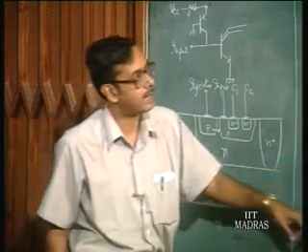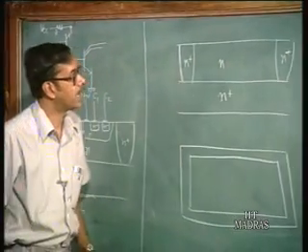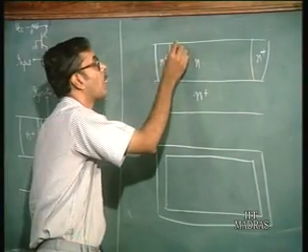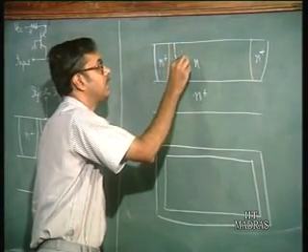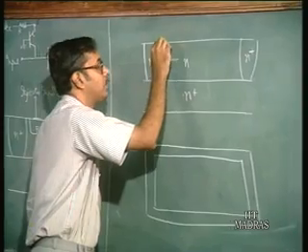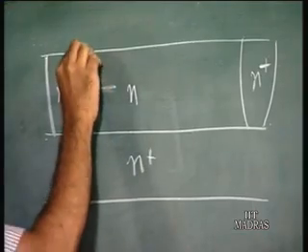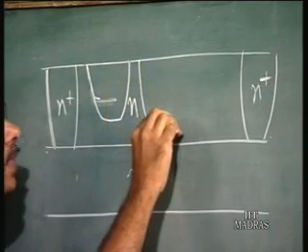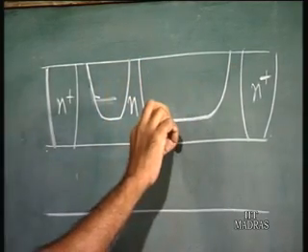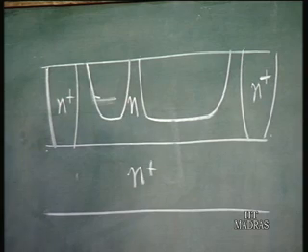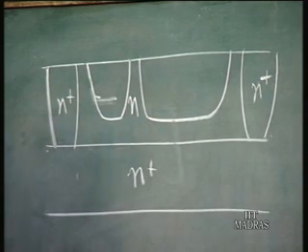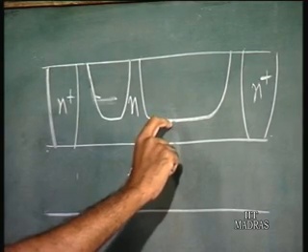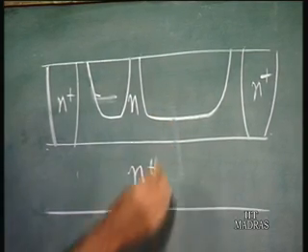Okay, so you have a guard ring like this. You first make the guard ring, and then you do the p diffusion to make the p-n junctions. You should make it as deep as possible, so that this region, the N region, which is actually the lightly doped region, is as small as possible. The thickness of this N region is going to be as small as possible.